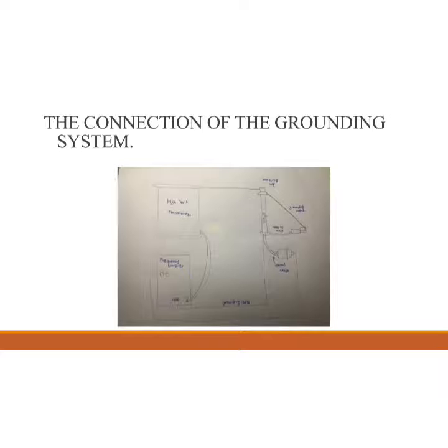Based on the manual book, VM1 and VM2 are for measurement, while VM4, VM5 and VM6 are for DC. Be sure that the maximum voltage is 7 VRMS, and while doing the lab, make sure the door is closed and in interlock.